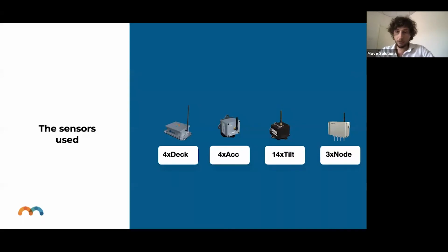So it's a real case study, a pre-stressed concrete bridge, and we placed 4 deck sensors, 4 accelerometers, 4 tilts, and 3 analog nodes. So it's a complex bridge.